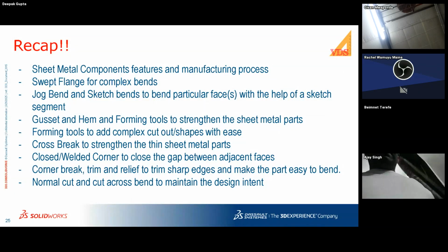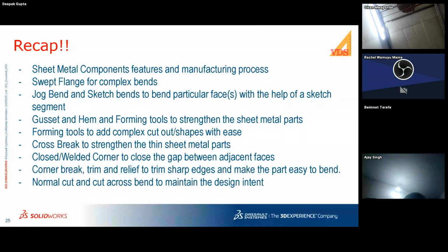which helped us to remove some of the unwanted material from the part. And we looked at the cut across the bend, which could be helpful to maintain the design intent, and the steps were easier. Just unfold your part, create the cutout either through or to a certain thickness, and then fold it back.